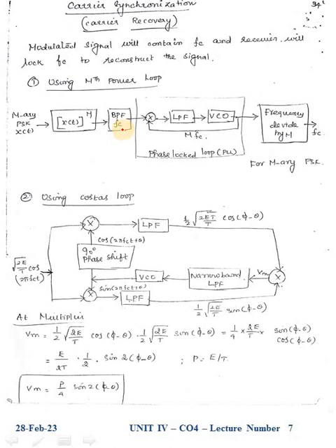The remaining unwanted frequencies are eliminated with the help of this BPF. So the higher order harmonics after the power level converter are eliminated except the carrier frequency. In this step we identify our carrier frequency, but that carrier frequency has to be maintained throughout the transmission. For that we introduce a phase lock loop, which is called PLL.